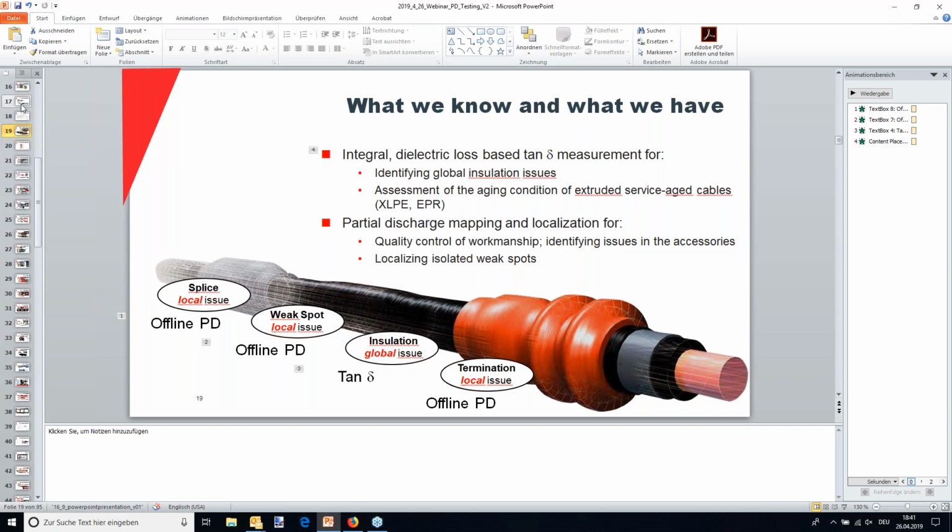Right, well, excellent. Next question is, what is your take on MV cable rejuvenation? Does it really work as a long-term fix, or am I buying a few months when the cable replacement is really needed? Okay, so I assume that you had some visit from our friends from Novinium. Novinium is doing, for instance, these cable injections. And you have to say, from a chemical point of view, it works to a certain extent. The problem is, with solid dielectric cable, when you change their dielectric properties, you see big changes in what you measure during the condition-based testing.